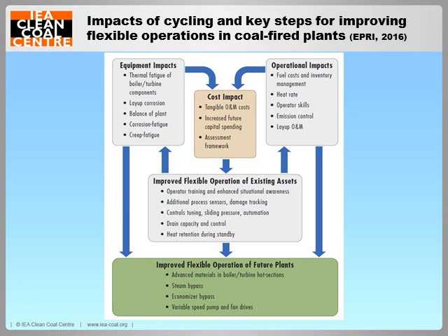Operational changes due to improving or increasing the flexibility of a traditional and/or modern coal-fired power plant include faster load ramps, more startups, more frequent load changes, more frequent minimum load operation, and reserve shutdown. The impacts of such operational changes on plant operation and maintenance include increased fuel costs, increased number of thermal cycles, as I said, the cycling, reduced plant efficiency, maintaining cycle chemistry, increased corrosion, increased component wear and tear, and impact on downstream emissions control technology devices.